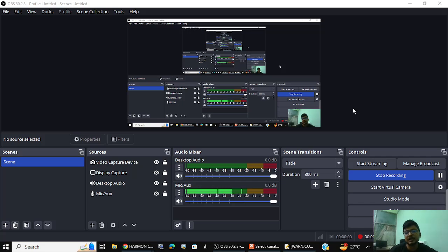And secondly, we can run the simulation for a longer duration or for a large number of steps. If it is transient, then for a longer duration, and if it is a steady state, then for a large number of steps until it meets the convergence criteria. So it is a judgment. So let's study this with an illustration.